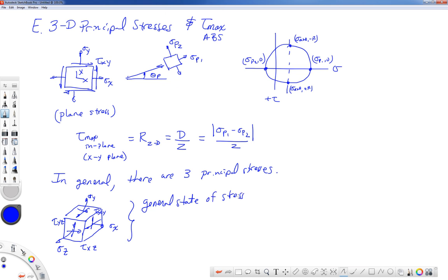The way that we've defined principal stresses is that they're the directions in which the shearing stresses vanish. If you can imagine taking that cube and rotating it in space, think of it like maybe a die from a game, and you reorient it in space, there will be 3 directions in which the shearing stresses on all those faces disappear. And they'll be perpendicular to each other. Sometimes I have a hard time drawing this, but I'm going to give it a shot.